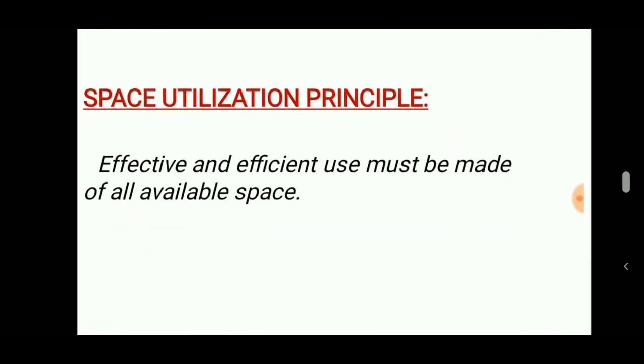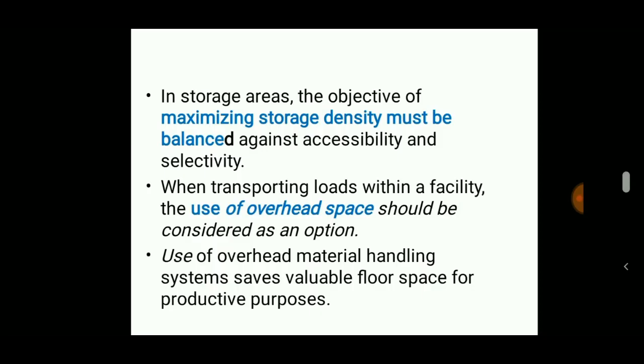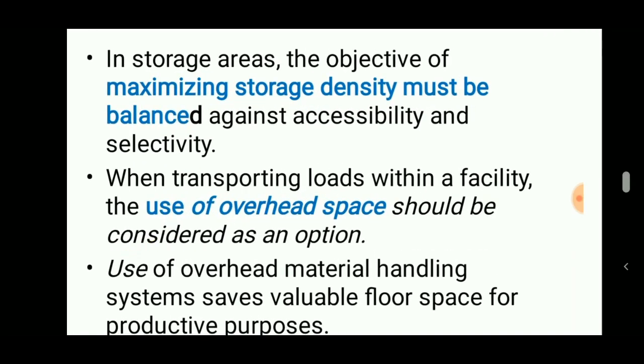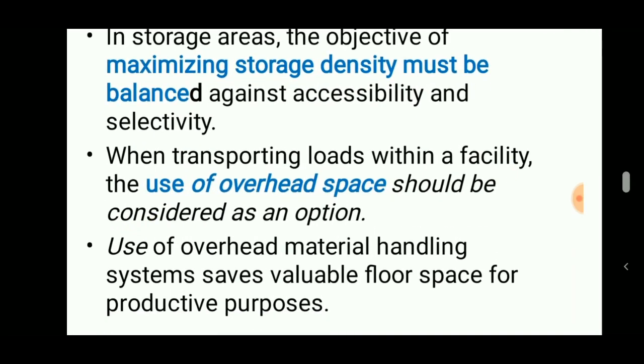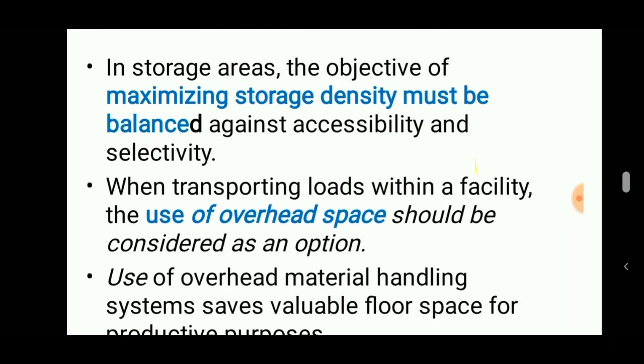And the space utilization principle, that is, the effective and efficient way of using the space. In storage areas, the objective of maximizing storage density must be balanced against accessibility and selectivity. When transporting loads within a facility, the use of overhead space should be considered as an option. The use of overhead material handling systems saves valuable floor space for productive purposes.